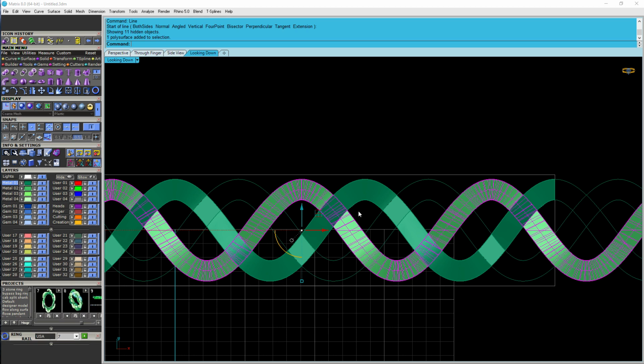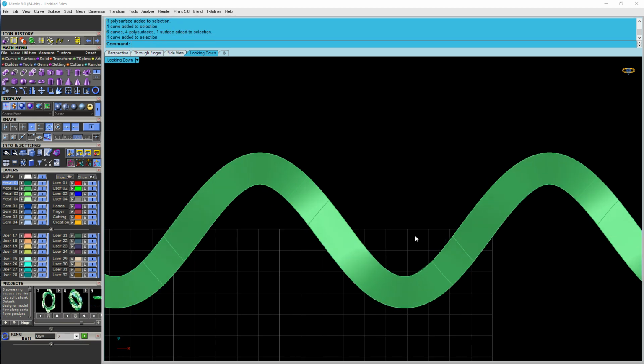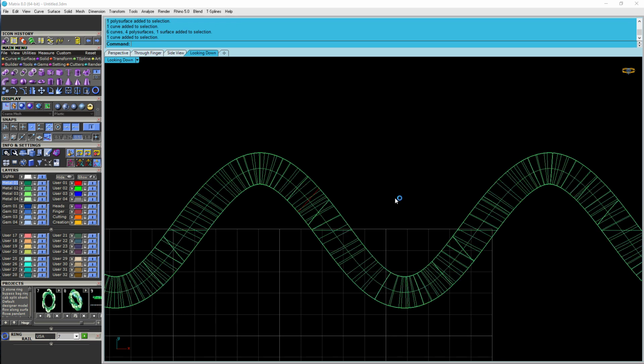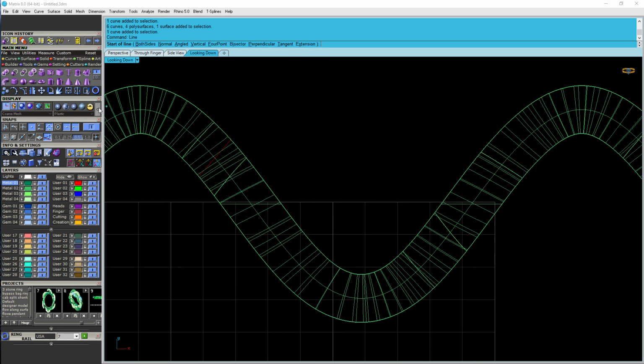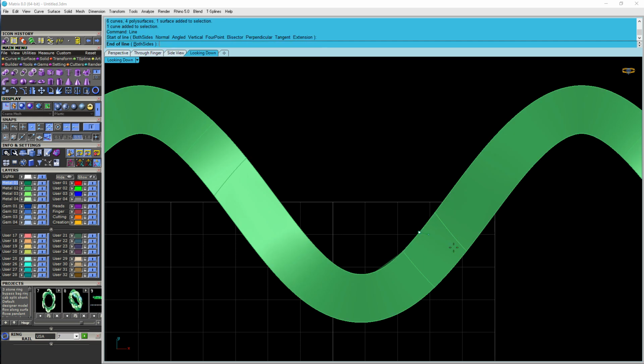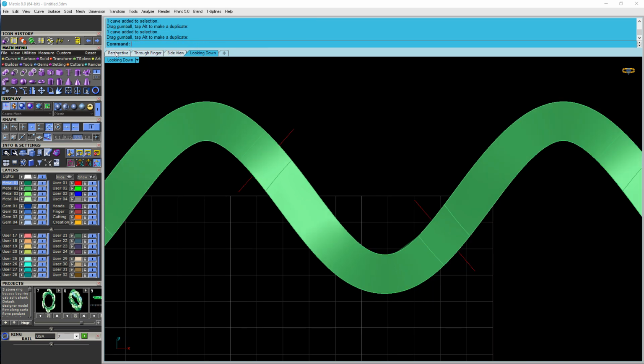Alright. Trying to make sure I'm doing the right thing here. So I got this curve drawn out. I'll put that on red, put this in wireframe. And then we're going to have one at this midpoint to the next one. So midpoint, midpoint. If you hold shift on a straight curve, we're gonna make a plane with that to use to split this guy up.